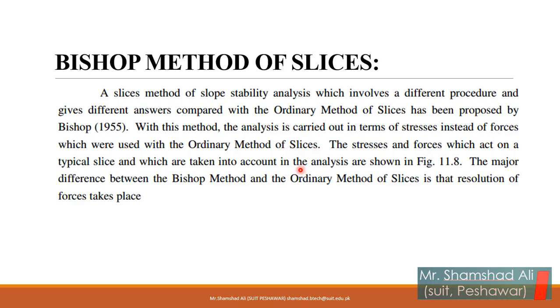Bishop method of slices. A slice method of slope stability analysis which involves a different procedure and gives a different answer compared with the ordinary method of slices was proposed by Bishop in 1955. With this method, the analysis is carried out in terms of stresses instead of forces, which were used with the ordinary method of slices.